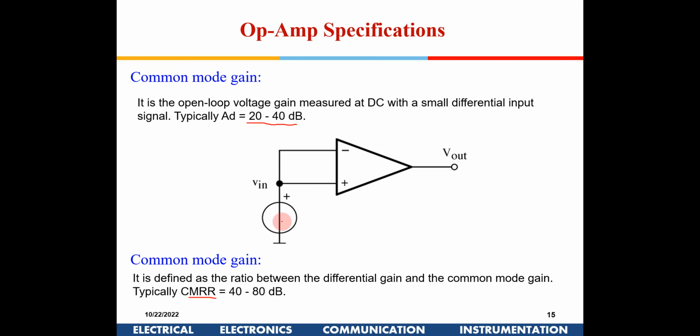There will be so many specifications, so to meet them you will have to compromise somewhere, correct? How to reduce the common mode gain? If you remember, the tail current resistance has to be increased to the maximum. For that you can have a cascode structure, but then the headroom will get affected, so the input common mode range will get affected. So those are the issues.